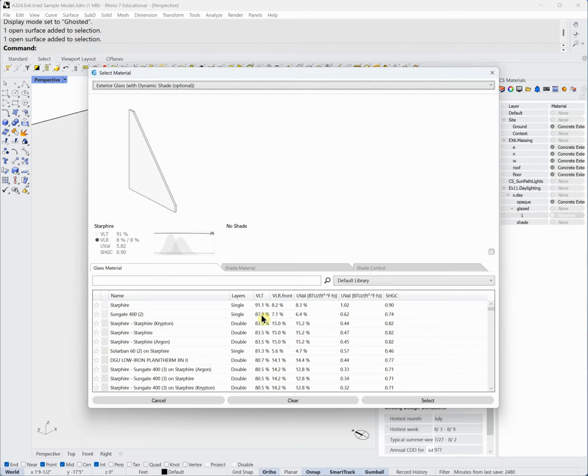So it's going to be high. It's going to be 91 or 85 or something like that probably. We don't have an infinite choice here, and it's not easy to make your own glazing materials, so just pick one of these. Anyway, in class we can talk about what's the best choice, and I will. In Old Westbury we can measure the plexiglass I have and get a good number. We can also get the solar heat gain coefficient for that value with the tool I have. But there's not a problem with just estimating it either, or looking it up in a chart.